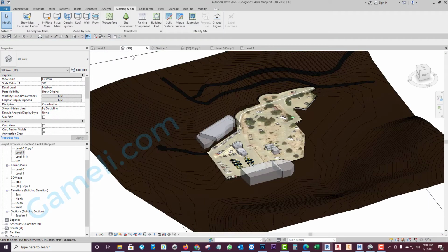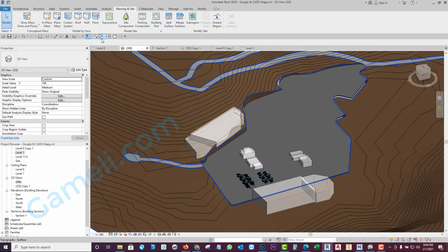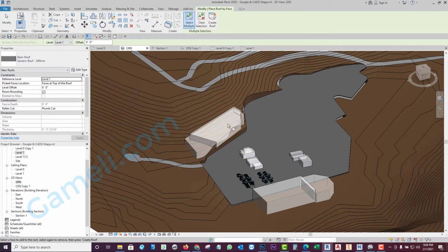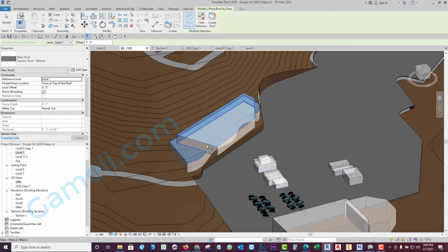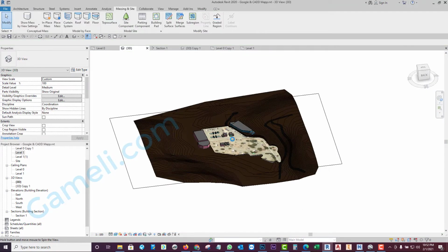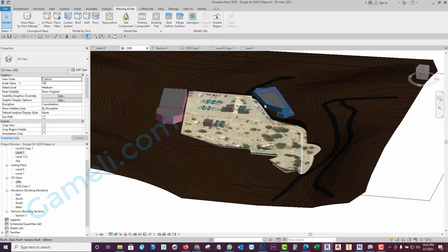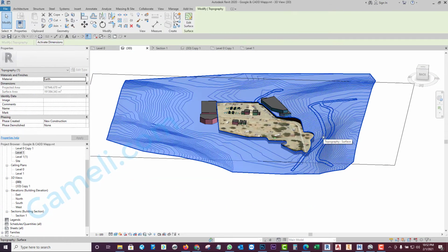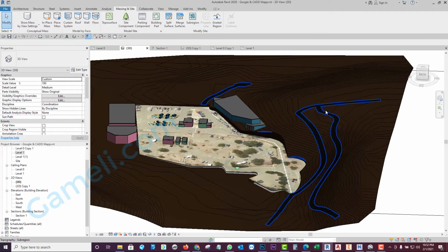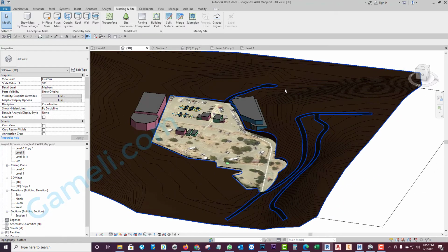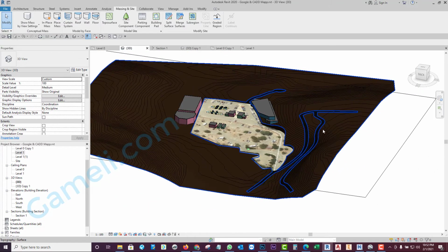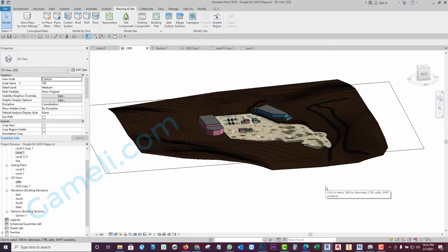So now I go to 3D. I'm going to change it to shaded so I could navigate faster. Let's convert this into building components. Roof, I'm going to use the basic roof over here and over here. Okay, so I converted all the walls and roofs from massing to regular walls. So we have this in Revit, alright? I could change the material to this road, or do some of the landscape or anything that you want to do around. But essentially this is what you get in Revit.